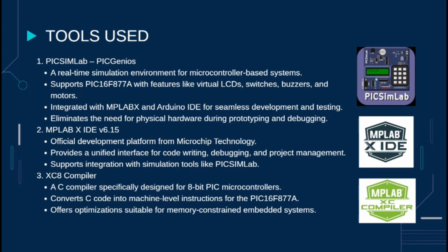These are the tools which are used in this project. First one is PICSimLab. It is a real-time simulation platform that emulates the embedded hardware, that is the PIC16F877A microcontroller. It provides all the virtual peripherals like switches and LCDs so that there's no need for physical hardware. We can test them online itself.